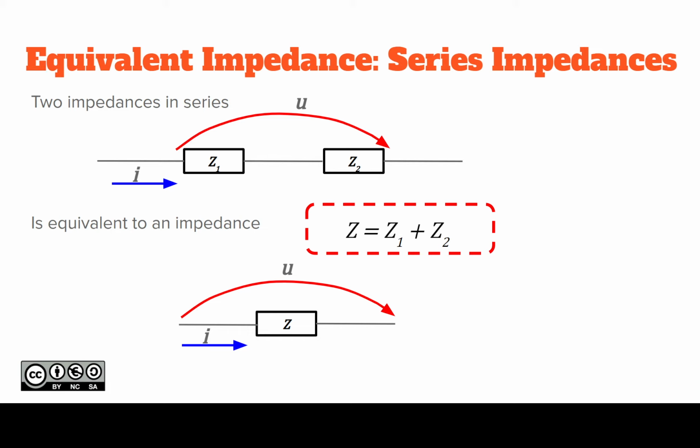In series, you just add the impedances. And there you have the imaginary unit sometimes involved. That's not a big deal. There are plenty of different math tools that you can use to calculate the complex numbers, and pen and paper is still a valid method.